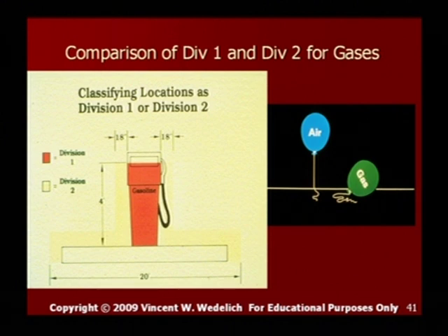And if there's an area where, let's say right here, if this went down like a little sump area, that little area down there would be a Div 1 location. So if there's a ditch or a little submersion, then that would be a Div 1 location.